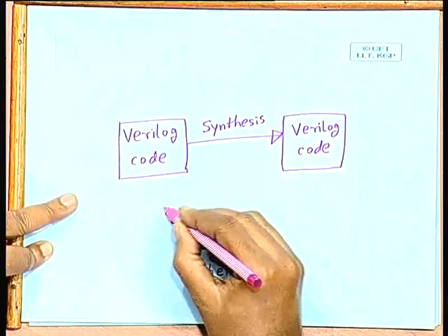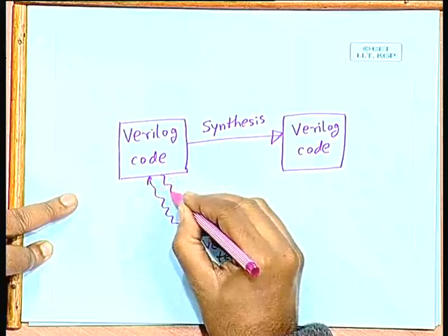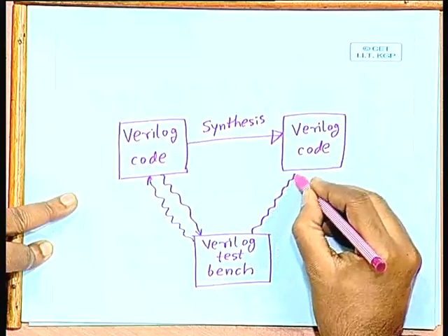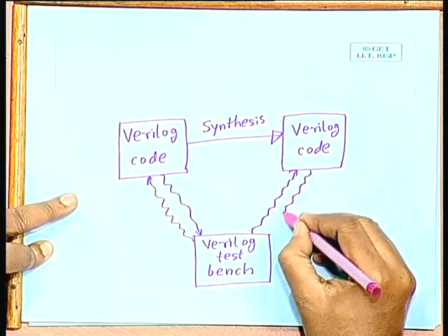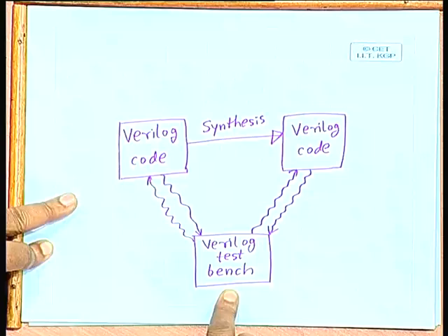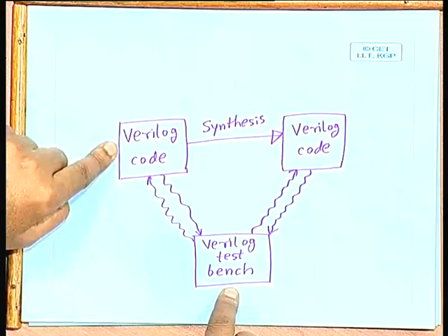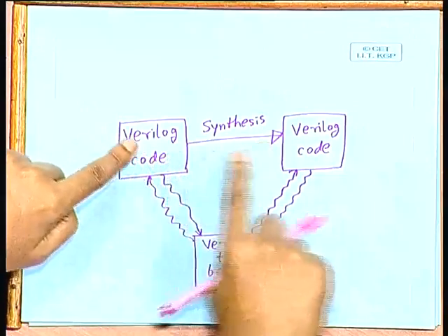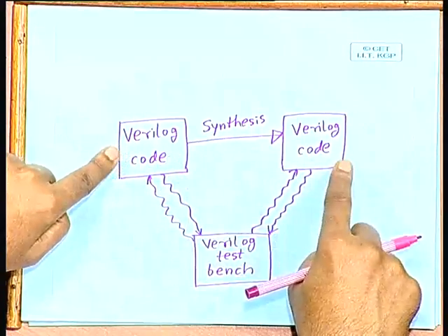So, exactly during simulation whatever you are expected to do, that is done by the Verilog test bench. So, the same Verilog test bench may be exciting this code and evaluating the response, and also it can be exciting this code and evaluating the response. The same Verilog test bench program can be used once to check this and another time to check this, or to compare whether the outputs of the two are the same or not.